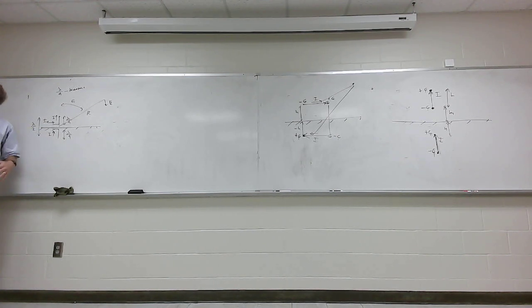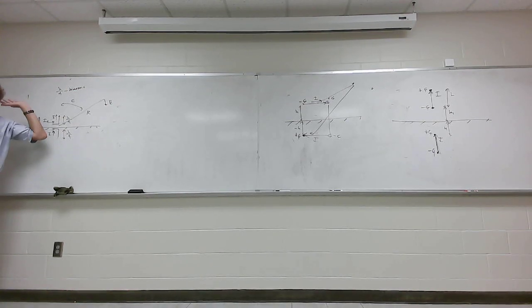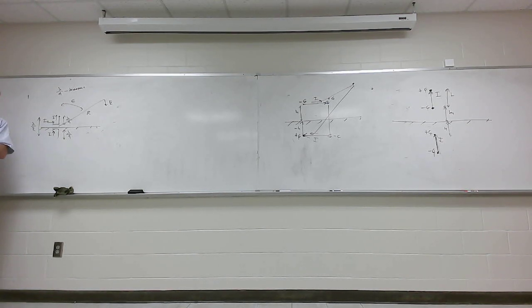So exactly half the power is radiated in a quarter-wave monopole compared to a half-wave dipole because it only radiates in the upper plane. Y'all see that? Which means the radiation resistance is exactly 1/2 that of the dipole, because the power radiated is 1/2 I naught squared R rad. If I naught is the same, R is the only thing that can vary. The radiation resistance comes down by a factor of 2.